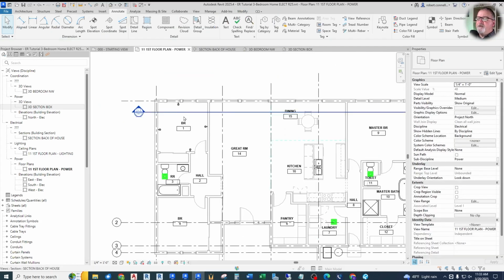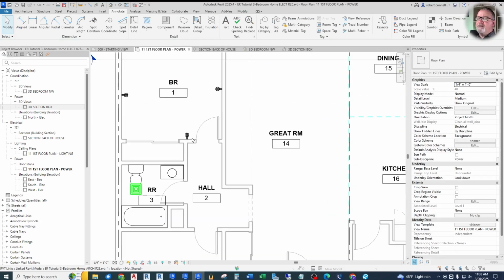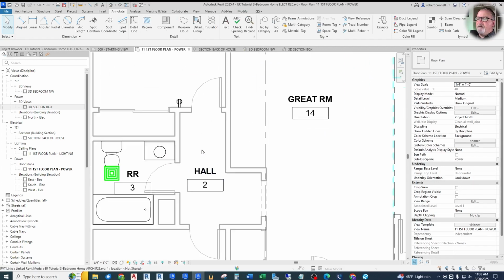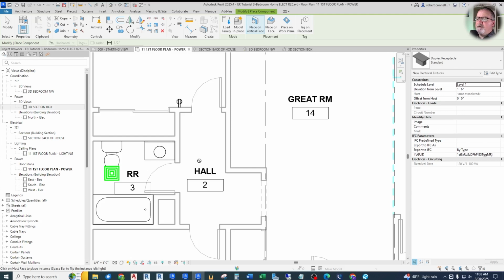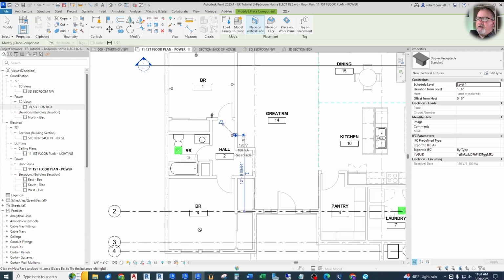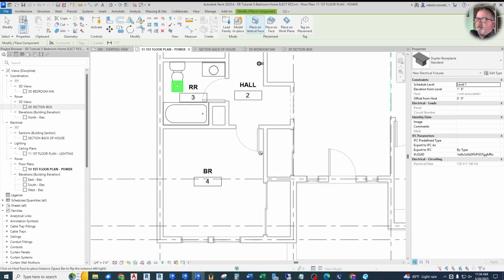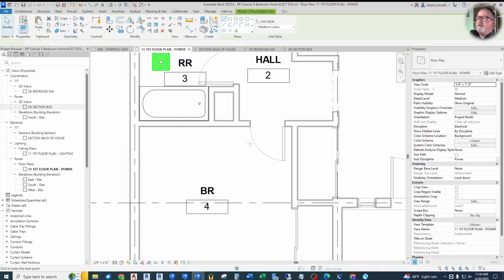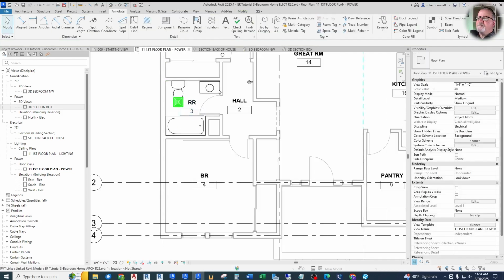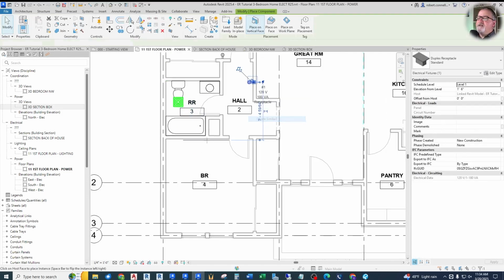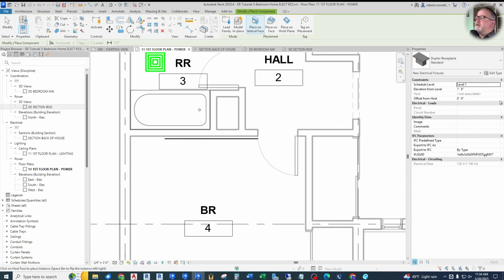Now, we just go through the rest of the house and add receptacles like that. If you look in the code, you'll see that if your hall's greater than something like 10 feet, we need a receptacle. I think it's a good idea anyway, whether it's required by code or not. So we can put a receptacle, say, in the middle of that wall. Down to this bedroom, our closet's in a different location. We have different rules. So we want to go through this and make sure we're not further than 6 feet from the door opening. Let's go to about 5'10". Again, create similar. These are all coming in at 1'6" height. You can tell over here.